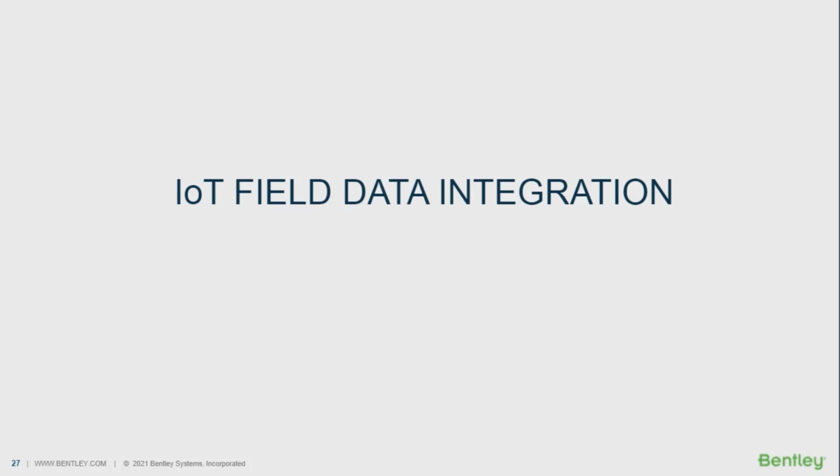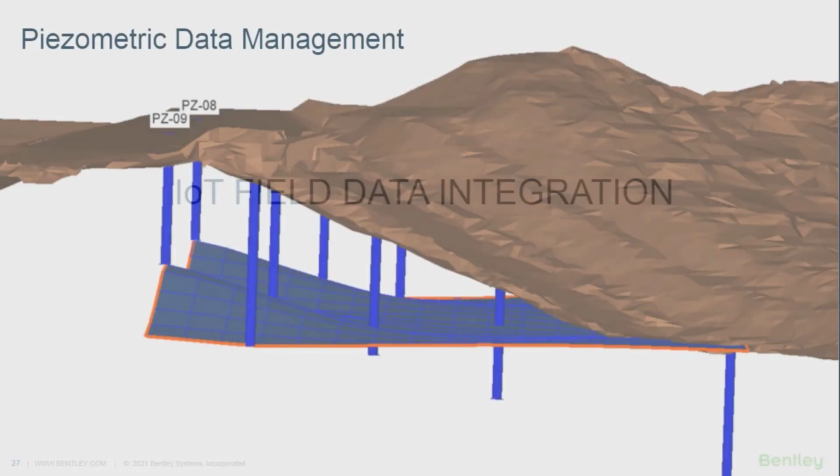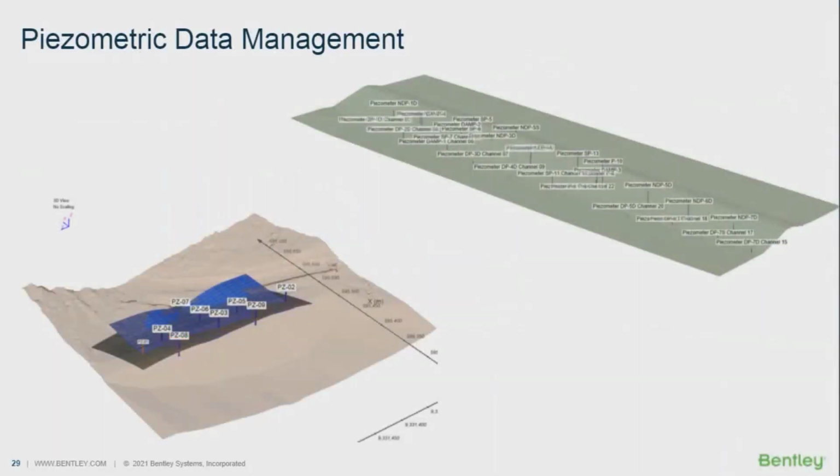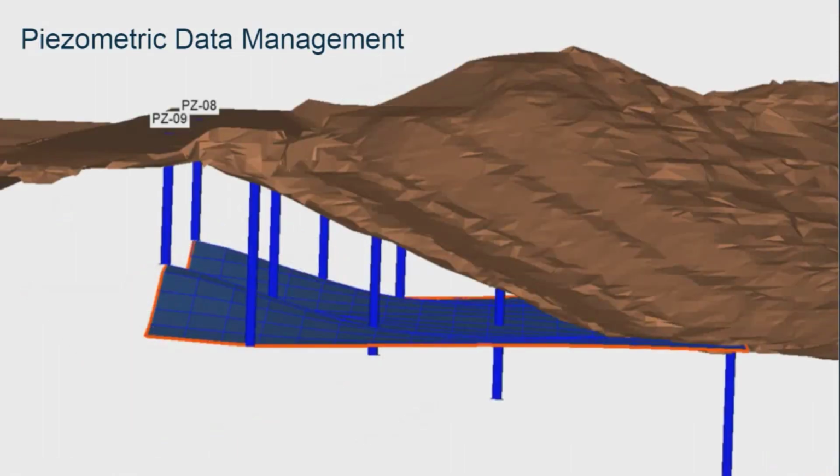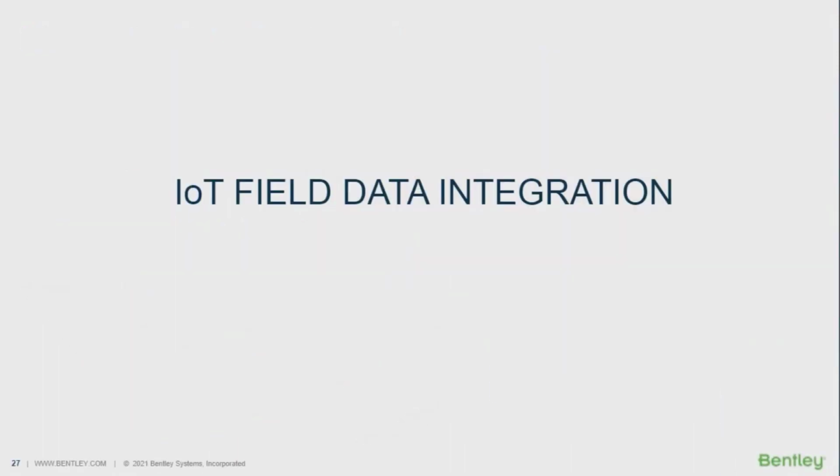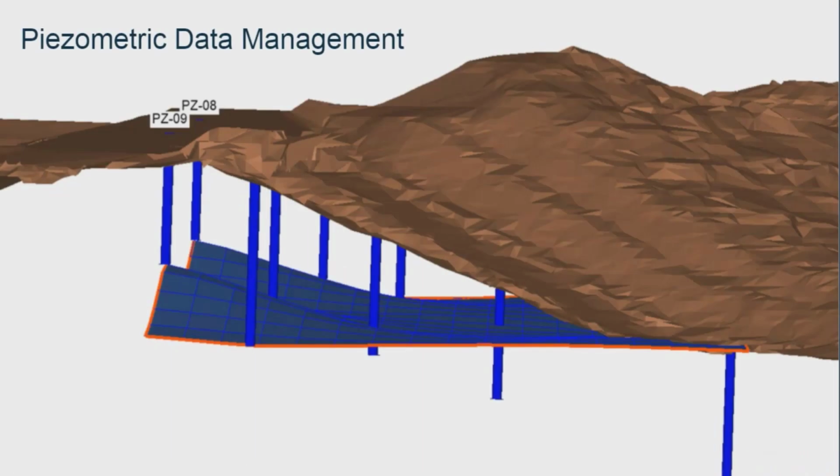So in that sense, if you have instruments, equipment that measure the behavior of a certain parameter in the field, it would be ideal if you could include it in the model and make the proper adjustments based on this connection. So in PLAXIS Designer, we can include the piezometric data management.